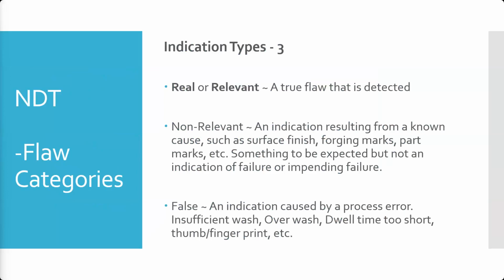When you do your detailed visual inspection, most of the time, if you can see flaws from a visual inspection, and it's a part that's going to need NDT, by the point that they're visible, it's definitely going to cause the part to be not serviceable. If your NDT requires you to find a crack that's not visible to the naked eye, and you can see a crack that is visible to the naked eye, that's probably bigger than the ones that are too small to see. So that part's not going to be serviceable at that point.